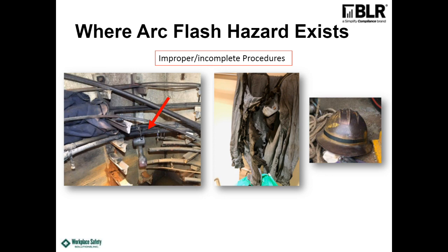And then it ionized the air and it traveled. This plasma caused a short circuit to go from phase to phase. So the single-phase fault in 480 turns into a three-phase fault very often if it lasts enough time, a few cycles. That's what happened, and it ended up being some significant burns as a result. Now, this would not have happened if you had an insulated screwdriver. Not that you would want to do this in a live state anyway, but that would have prevented it from happening.